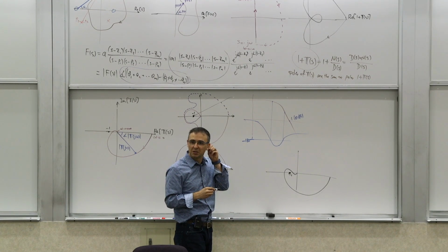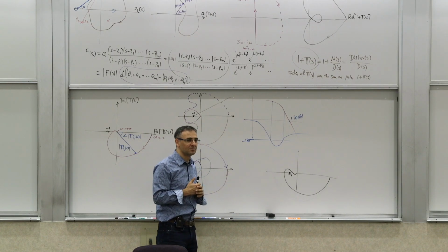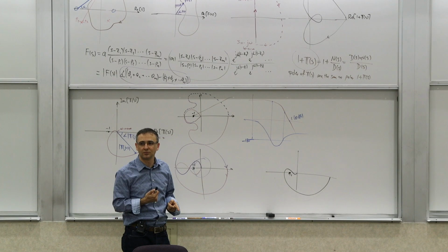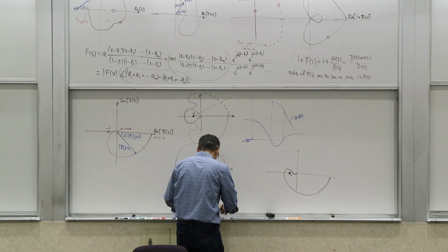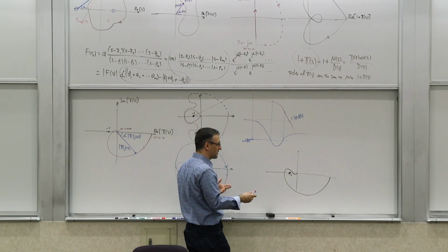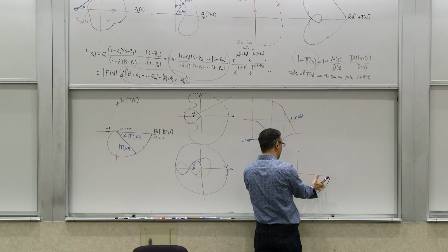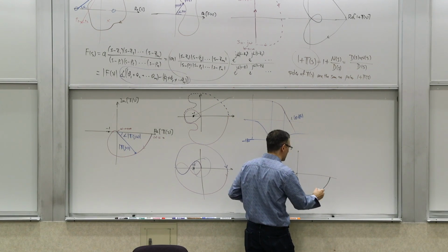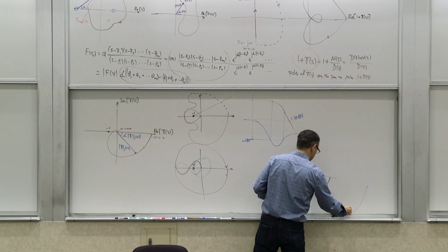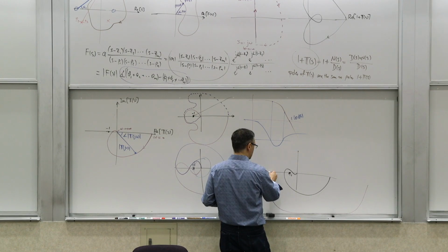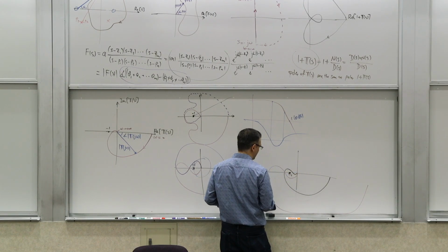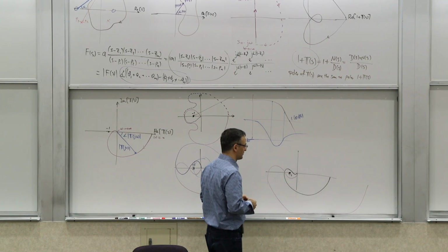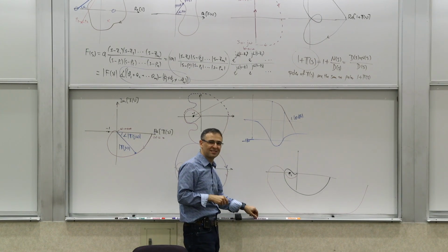So is it stable or unstable? Unstable, because you're encircling the point -1. Now, if I increase the gain of this thing, or increase the feedback, let's say I do it in a scalar fashion, everything scales up. This becomes a bigger plot. So this becomes like this. It's a bigger version of that, supposedly. Now it became stable.